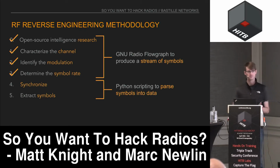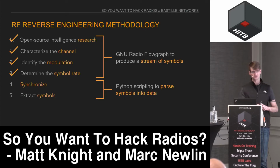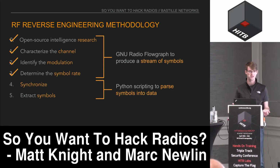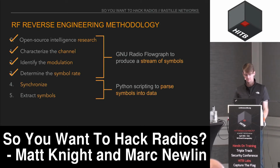This flow graph is essentially going to capture raw radio information using the SDR, do some math on it, and it's just going to give us a stream of 1s and 0s. Once we have the 1s and 0s on our system, on a disk, we can parse through them using any tools we desire, right? You can use any language, any workflow you want, because it's just a binary format, just like any other data. So we're going to implement that with Python, because Python's really easy.